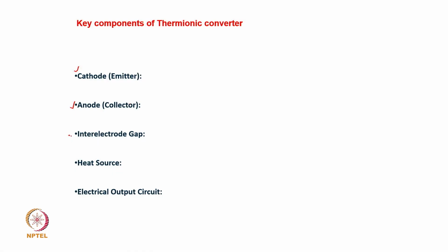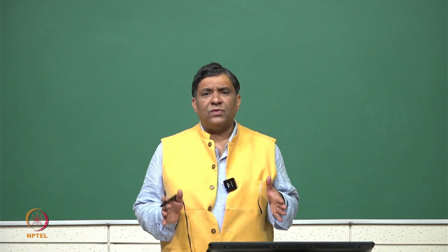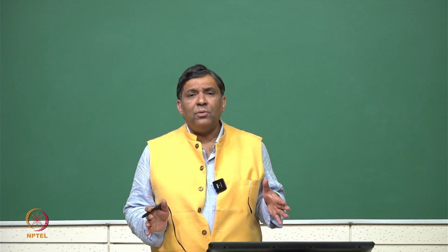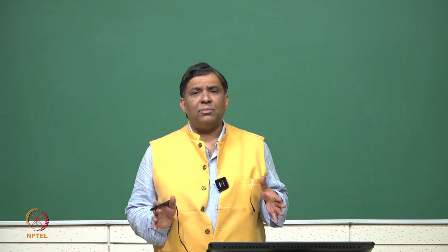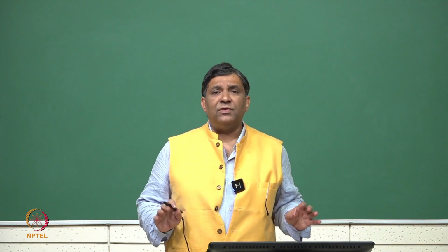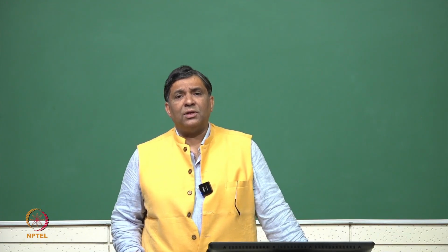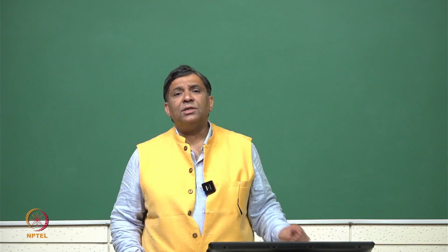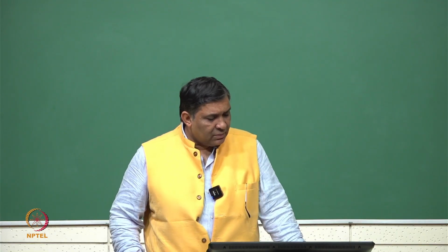Third is interelectrode gap. This is a very important thing which I mentioned in the previous lecture. This interelectrode gap actually decides the overall performance of the thermionic generator, or it is one of the important parameters which decide the performance of the thermionic generator, and it has to be optimized.